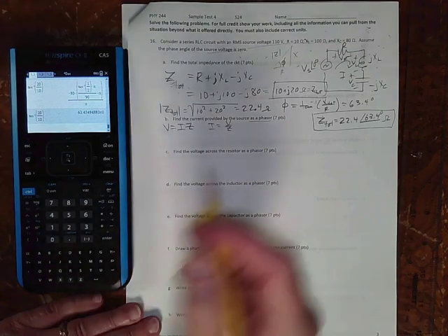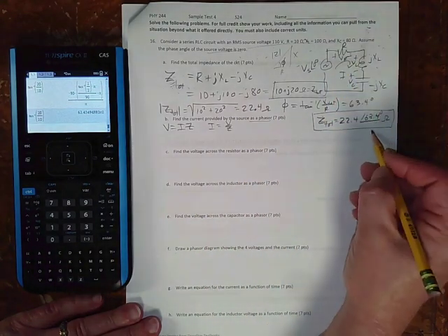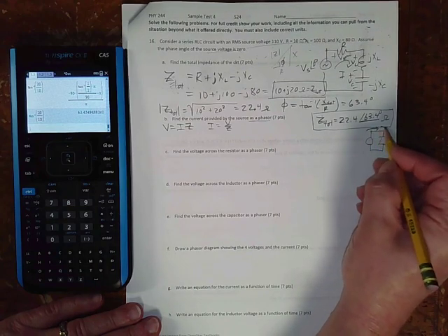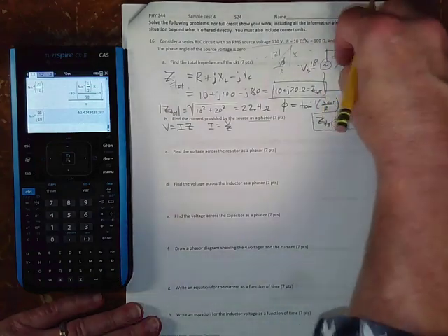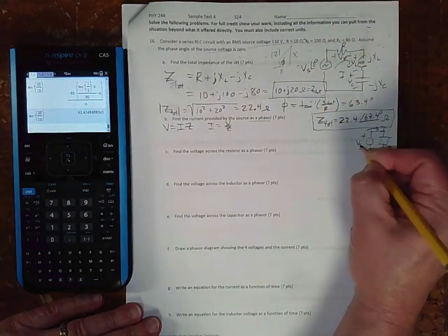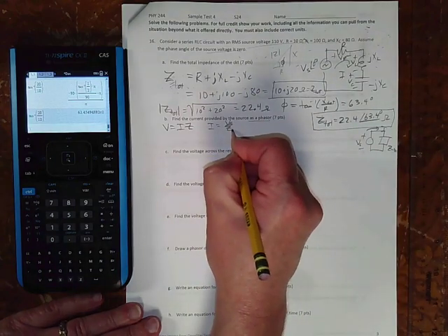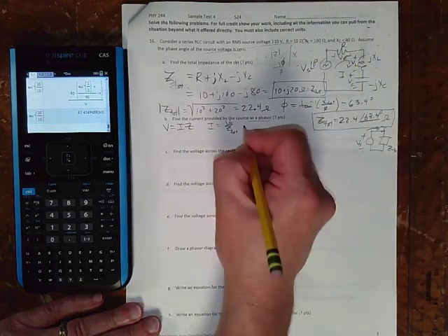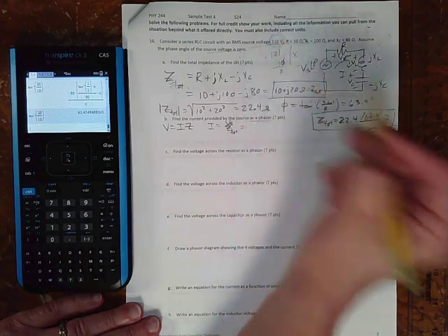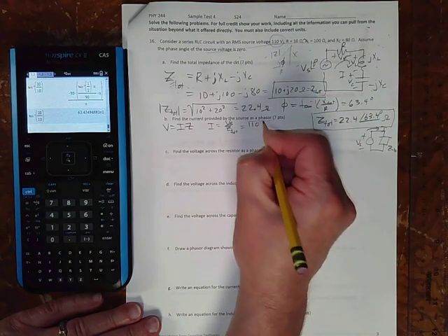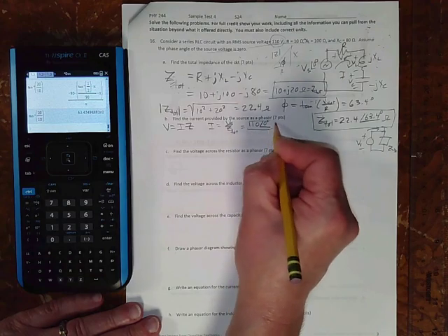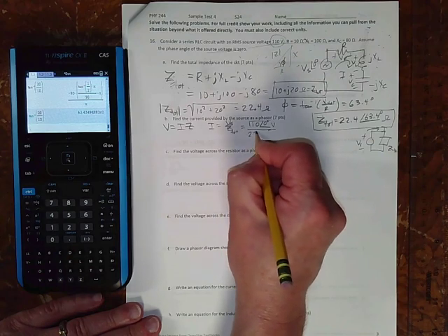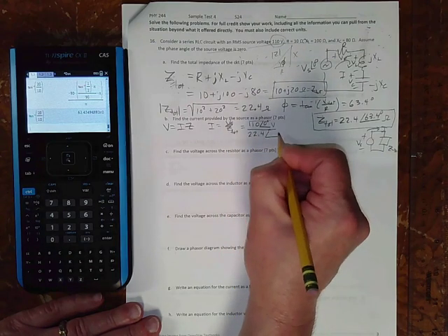Think of a little circuit here with the source and Z total. We have the same I as above, since all these have just been lumped into one, with the same source. So I is going to be V sub S over Z total, going from the generic Ohm's law into our specific case. V sub S is 110 at an angle 0 volts, since we were told to use 0 for the phase angle, and Z total in polar form is easier for dividing, so we'll go with that.